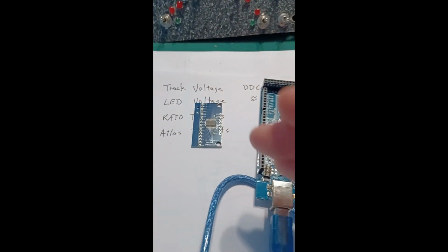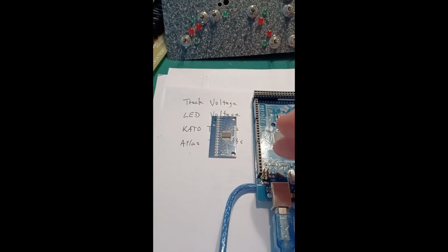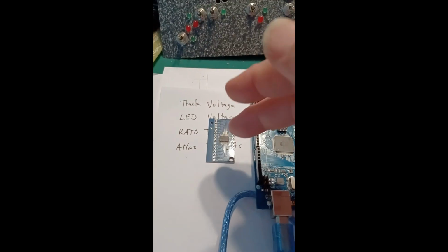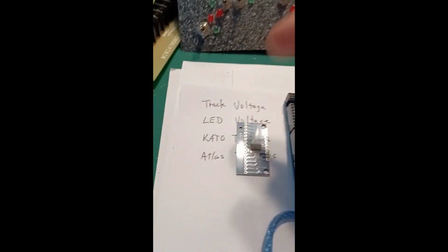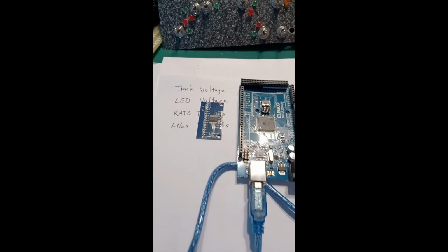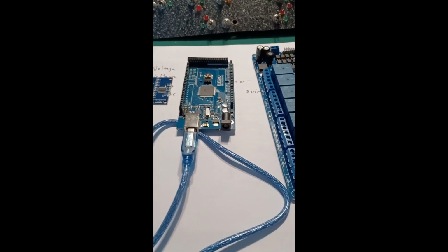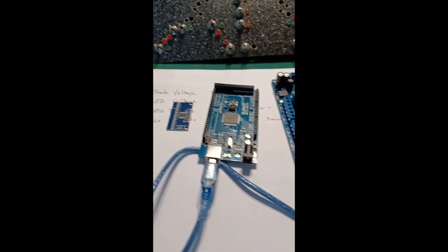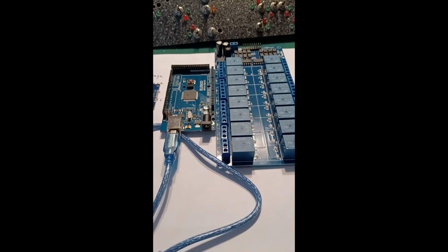By using coding, I can tell a given pin on the Arduino to send a signal to the multiplex board, and that multiplex board then will divide that up and send that signal to a specific one of these 16 outputs. It's a trick, it's done with wires. That's how I'm going to multiply the output of the Arduinos to be able to control the 40 relays.